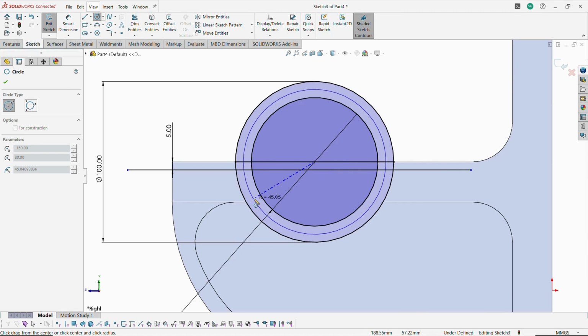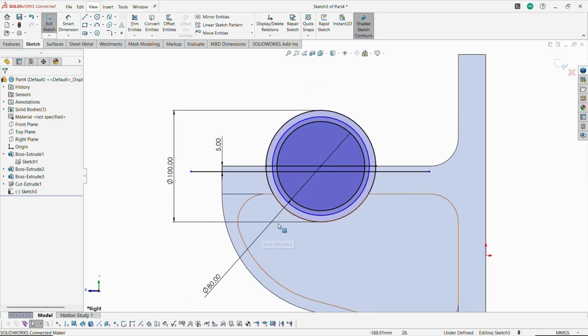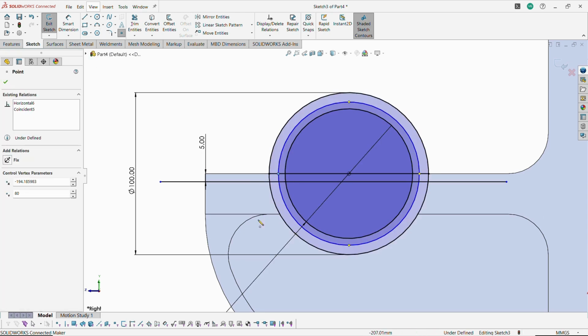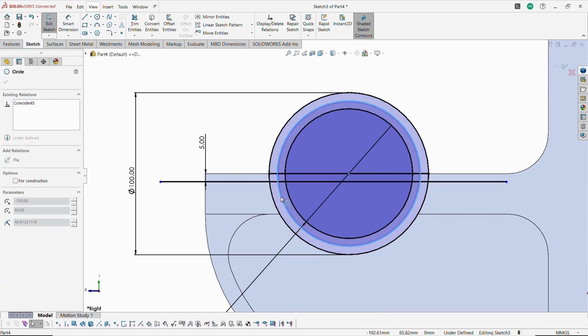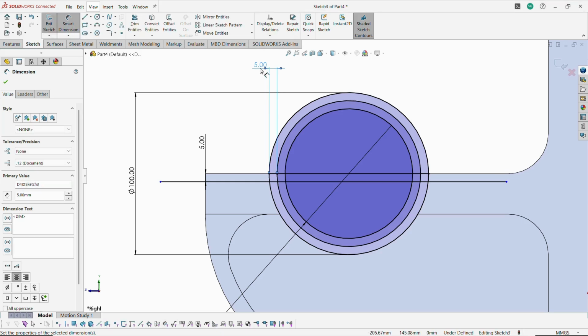Okay, from the center point, I am going to draw another circle. It must be placed in between this particular distance, that is the same distance. How are we going to achieve this? The total distance is only 10 mm, half of the distance is 5 mm. So just to mention this point and initiate the dimensional value of 5 mm. Select the two opposite points and mention 5 mm. A lot of profiles, both the line ones as well as a circle, are merged within each other.